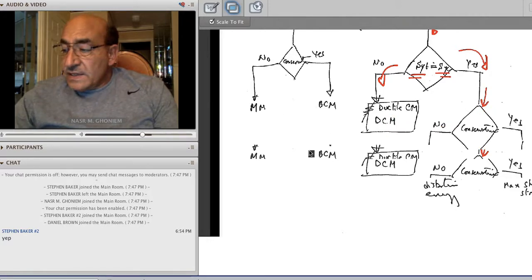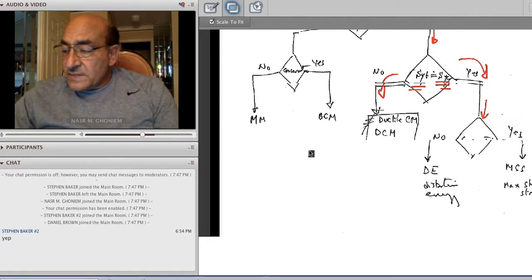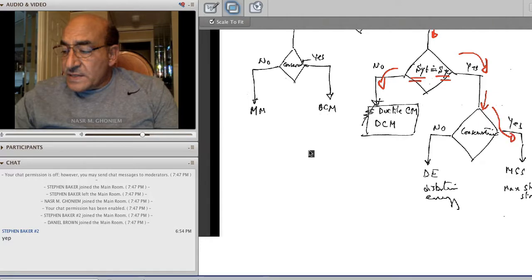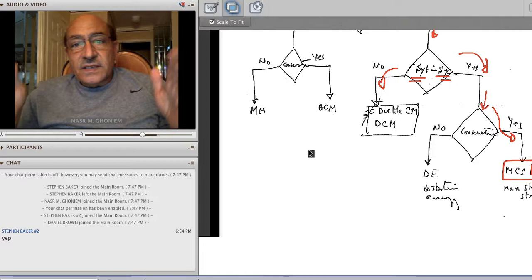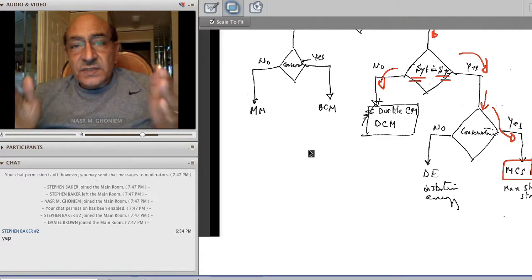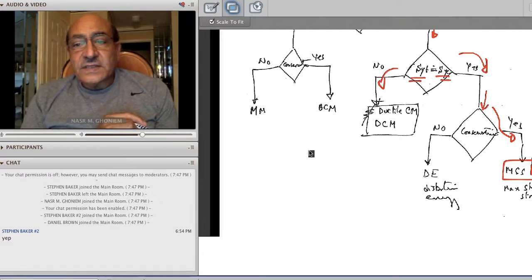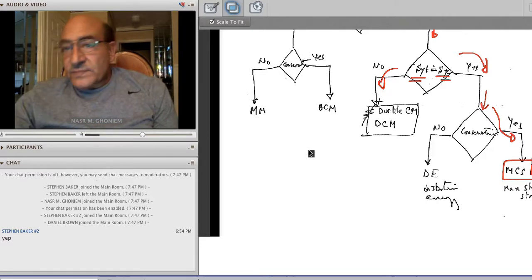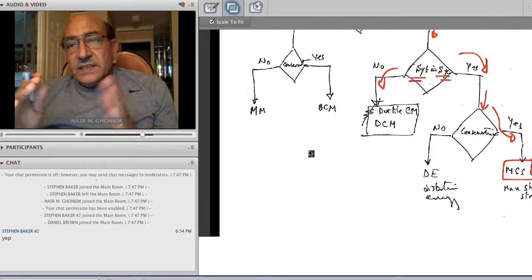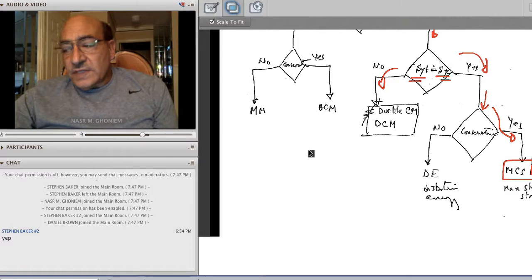If I don't know the data, then I go to be conservative, and the conservative is the maximum shear stress theory, which is inside the ellipse. So the hexagon is inside the ellipse, so it is more conservative because you're limiting the space for yield. Otherwise, if I have good data, then I can go this way, and I use the distortion energy criterion.